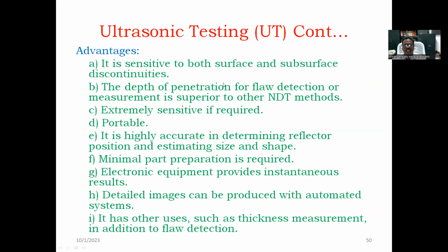Advantages: it is sensitive to both surface and subsurface discontinuities. The depth of penetration for flaw detection or measurement is superior to other NDT methods. Extremely sensitive if required. Portable. It is highly accurate in determining reflector position and estimating size and shape. Minimal part preparation is required.